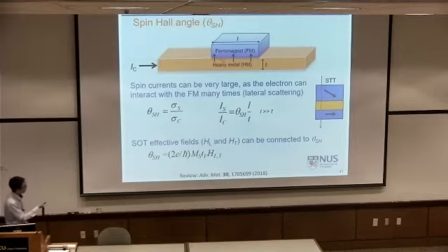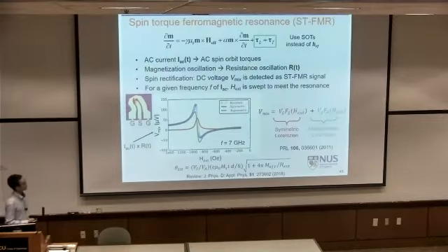And those two components, effective spinor angle and the SOT effective field, have some kind of linear relationship. So again, the bottom line is we want to increase those numbers as much as possible because that will decrease the switching current eventually. How do we quantify this spinor angle?